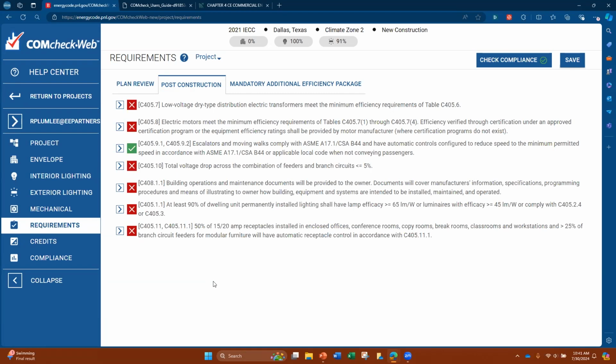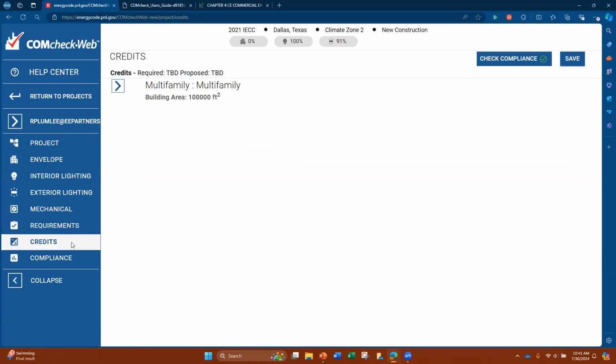And sometimes it's not their fault. Sometimes the supply house was short on some of them. They had to go with a different version. Well, that may change output capacity. It probably shouldn't, but sometimes it can, and they may do it on just a few units and not all. So verifying model numbers to me is a key item that you just have to do. If you don't do it, then you're not doing your due diligence to make sure they're complying with what they've told you they were going to do.